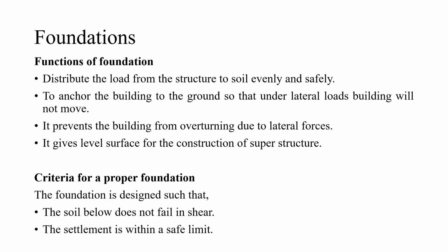The purpose of a foundation is to transfer the load from the structure to the soil and distribute it evenly and safely, and also to hold the structure firmly into the ground such that even under lateral loads the building will not move, and it prevents the building from overturning due to excessive lateral forces. It gives a level surface for the construction of the superstructure.